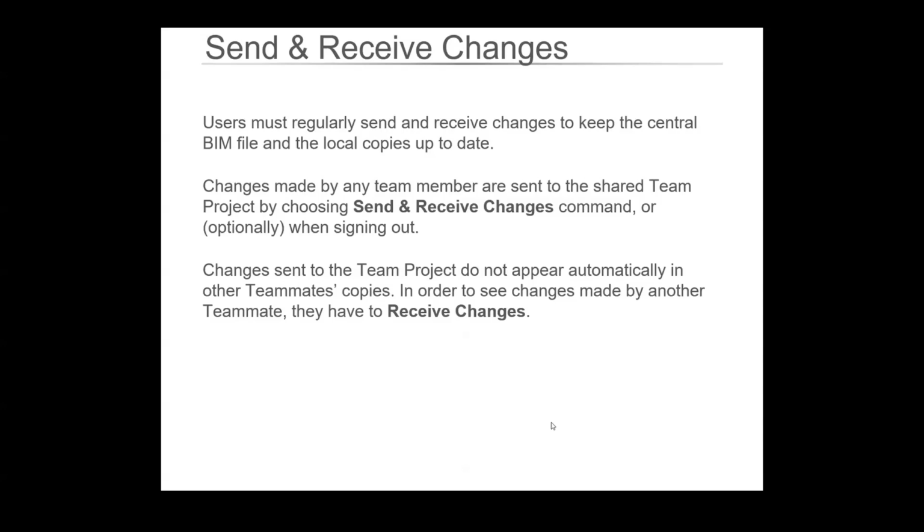So you're effectively helping your computer to work better. And the same with the send and receives on BIM Cloud and BIM Server. Don't turn up in the morning, work all day, and then send it at night and expect not to have too many problems during the day. You'll find you'll be sitting there waiting for stuff. So it's always a good start to improve performance and get rid of the beach ball.